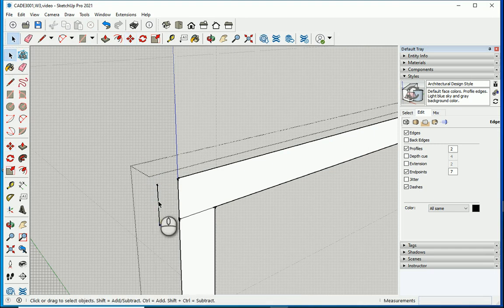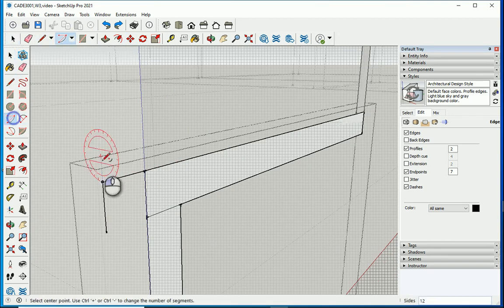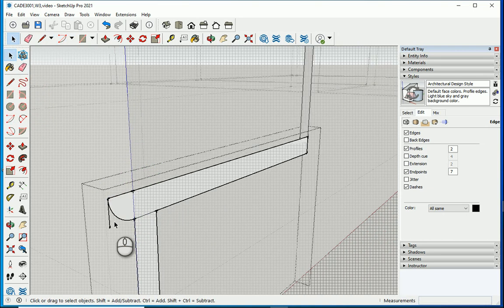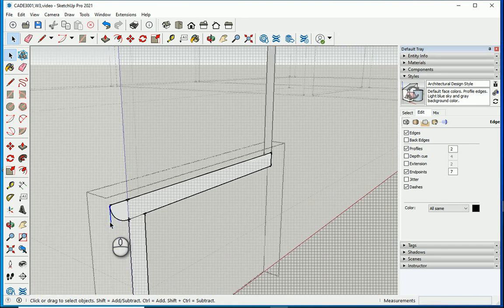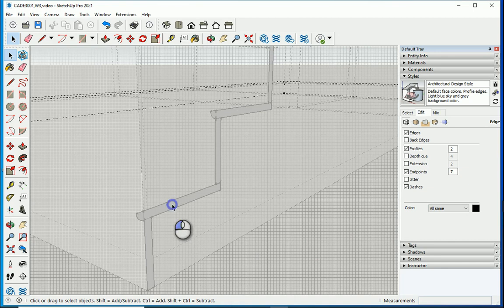Notice that if you hit space, it's going to move to selection. Then I'm going to type M. I'm going to go with another 1 centimeter. I'm going to go with one line here. So I want to go with arc, but I want to use arrow keys. If you use the left arrow key, it knows that it's going to be on the correct surface. So from here, over there, and over here, that could be better. And I'm going to delete this. And now you see that it's actually changed it for all of them.